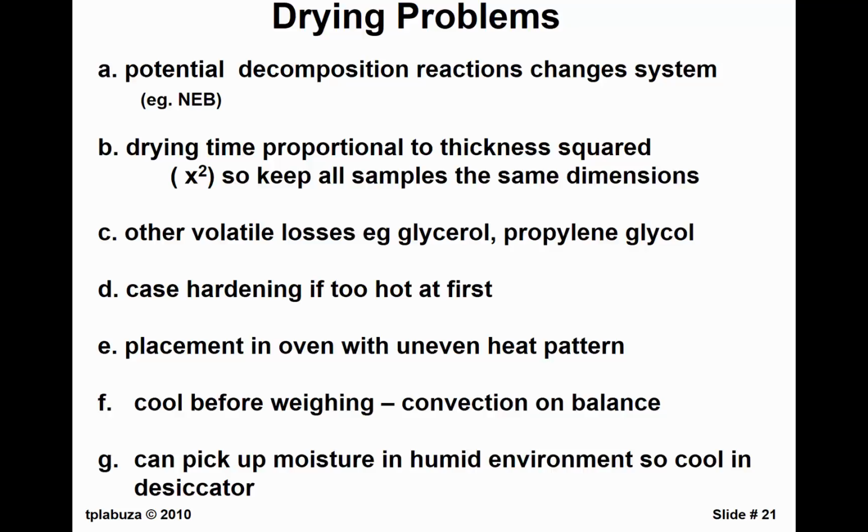If you dry too hot, with vegetables especially, the heat takes that pore that's losing water, and that pore now goes over its glass transition and it collapses. And so you get something called case hardening. And so you trap the moisture inside the product, and you're going to get a false reading if you use the standard time. So it's especially a problem with dehydrated vegetables.